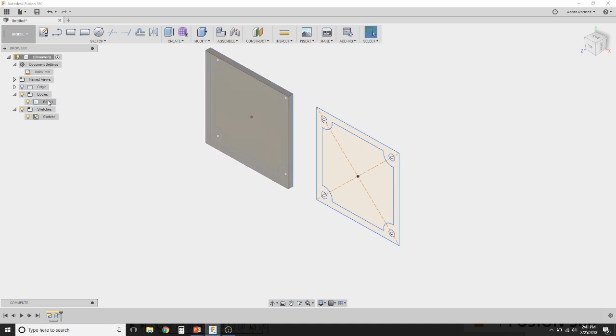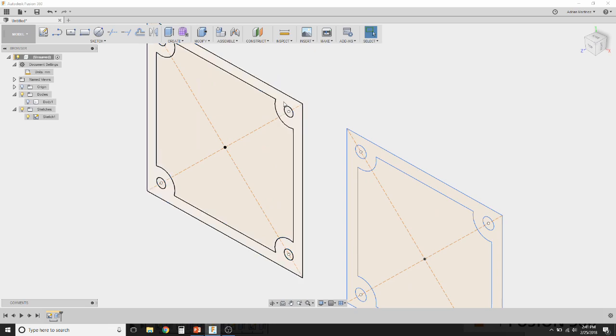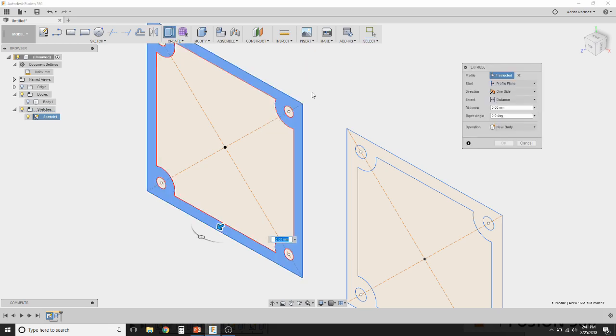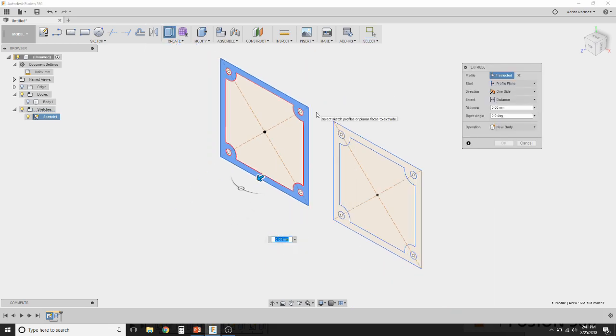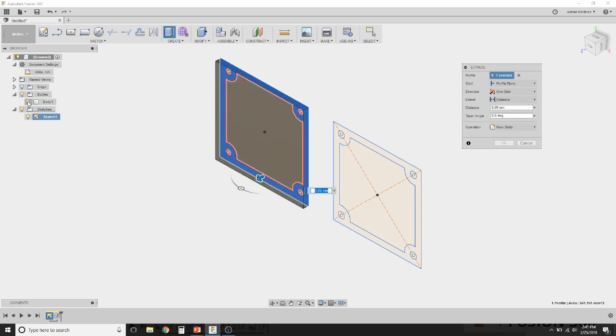This Body 1 represents the solid object that you just created. We're going to temporarily hide it by turning the little light bulb off. Now we're going to zoom in to the space that represents the walls of our box and click on it. We're going to right click and press pull. Now that we've done that, we're going to go back here and turn our body on, okay?